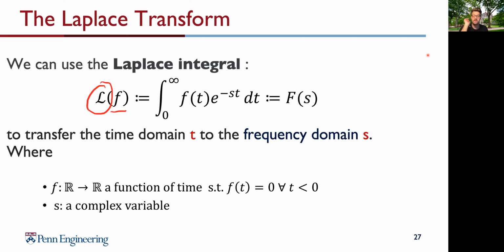Since it only starts at time t equals 0, it is capable of being used for most real signals f(t), which are plotted over the time t, and for the most common differential equations to calculate the reversible unique image function F(s). So to repeat it here again, we have something that exists in time domain t, and we transfer it with the Laplace integral to the frequency domain.